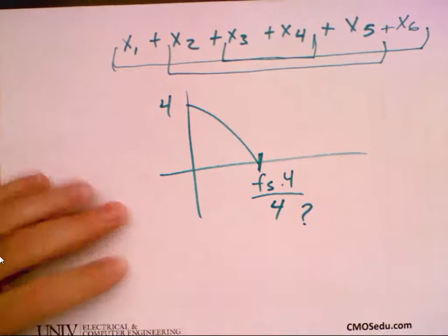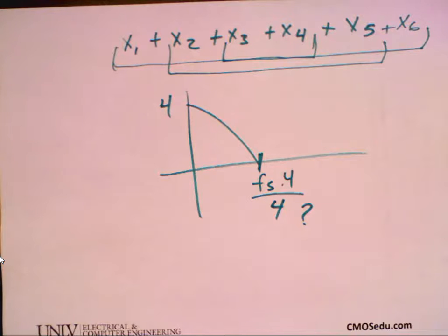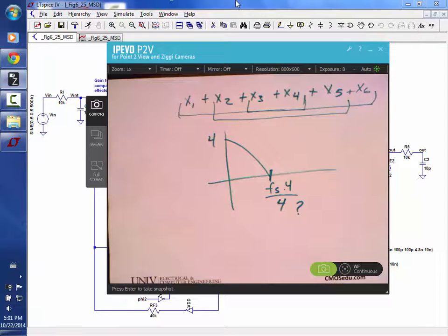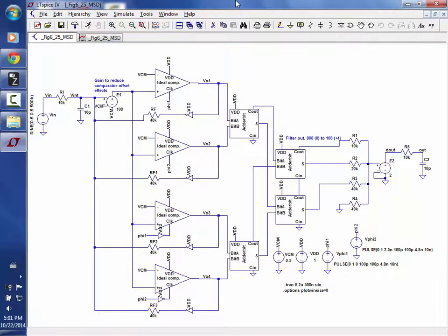Okay, so is there decimation here? There's no decimation. The key point I'm trying to get across, and again, I'm going to cover this next time, is when you're doing these high-speed things and you're looking at the bits and you see somebody adding bits together like this, you don't just go, oh, okay. You know that they're filtering your data. So it's going to come through and you're going to get an attenuation if you put a higher frequency sinusoid in here that's going to roll off at the sinc filter just by adding things together, okay?